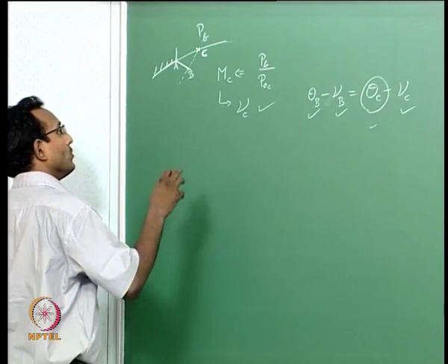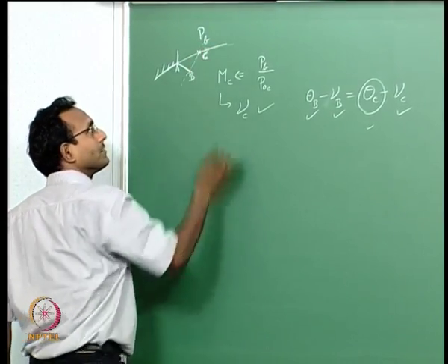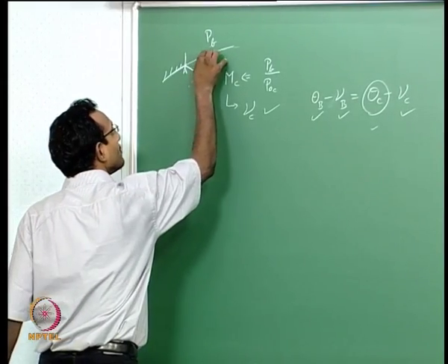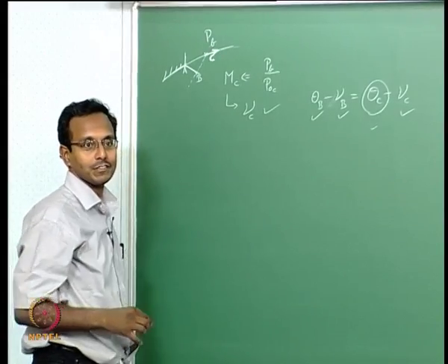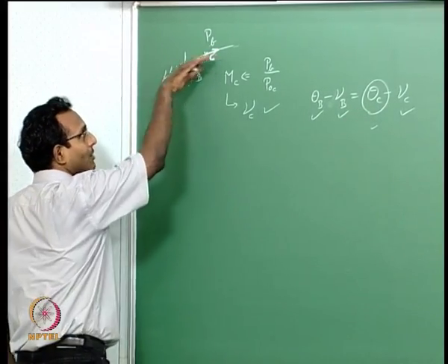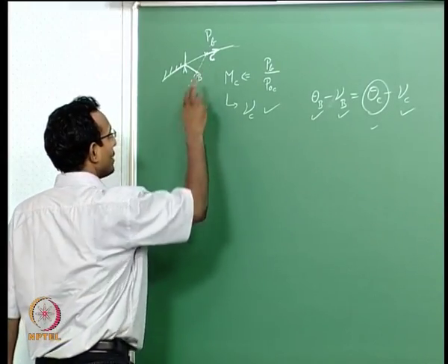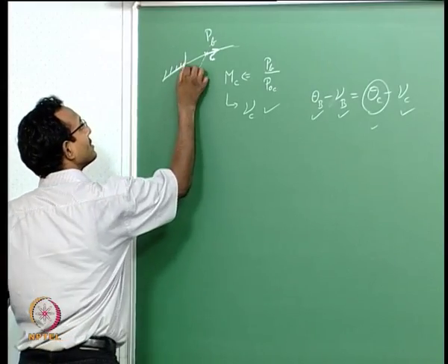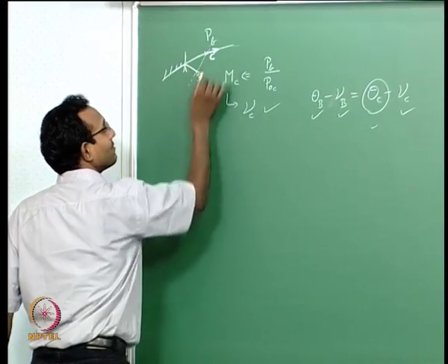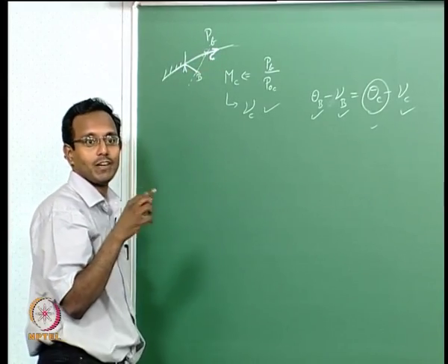Now, after we have found this, the remaining thing is to find the velocity direction. We know that the jet boundary will be going with some velocity vector value, some direction. So I know that at that location theta C is the angle of the velocity vector, that is found already, so tan of theta C will be my dy by dx at that location. But what I do not know is what this curve is here. If I do not know the curve, I cannot find the BC line intersecting with this curve AC. So now I have to find the point C, as in the location x, y of point C.